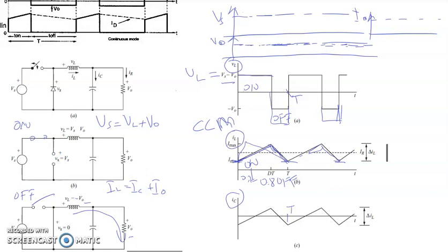And same if you shift your duty cycle higher, meaning instead of 0.8, maybe 0.9. You can see that the curve will ramp up slowly but ramp down very sharply. It starts at a certain level and will stop at the same level where it started. Okay, this is the behavior of your ideal inductor.